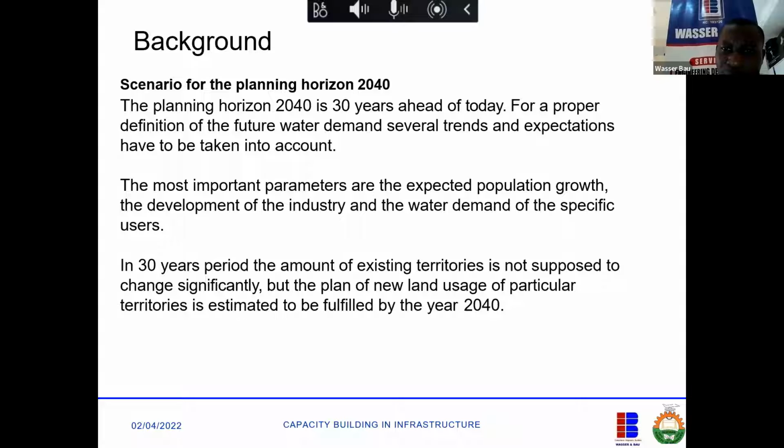That's just the point. Then if I expect that there will be a new university, a new school, a change of land use, and that change of land use can affect 20% of my development, then I'll calculate 20% of the population again and add it, and that will be 170. So my final value, what we call population equivalent, PE, which is a very important parameter for your design, will now change to 170. So 170 becomes my design baseline. Okay, so that's just what this is talking about.